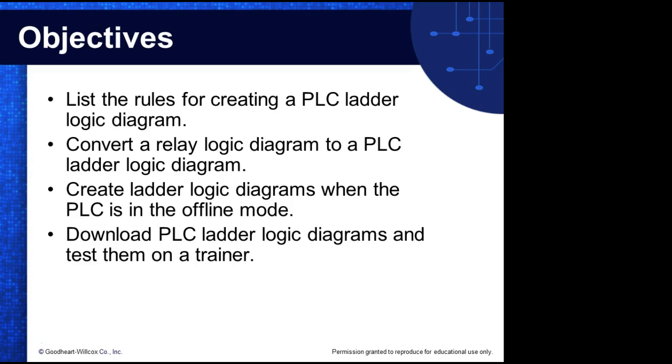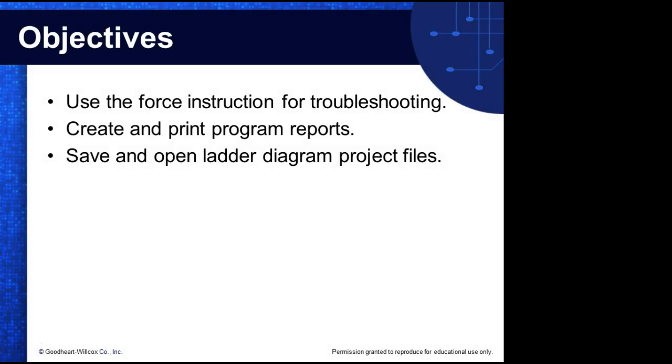Create logic diagrams using PLC in the offline mode. Download PLC ladder logic diagrams and test them on a trainer, which is what you're going to do, right? We're going to play around with the force instruction, which allows us to literally force these devices into another state. Create a print program. We're not going to do that. We are going to save an open ladder diagram project file. Okay?